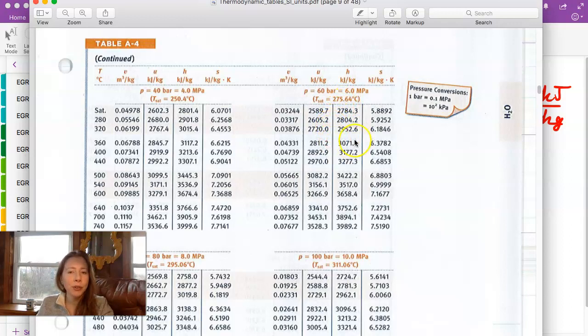Then we multiply that by the difference between the upper and lower limit: at our higher pressure, we're at 3,246.1 kilojoules per kilogram, and we subtract 3,277.3 kilojoules per kilogram. Also notice that when we increase pressure for the same temperature, we reduce enthalpy. So you should have a negative number in there, and we will ultimately end up at something slightly lower than 3,277.3.